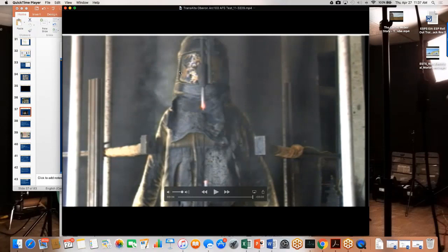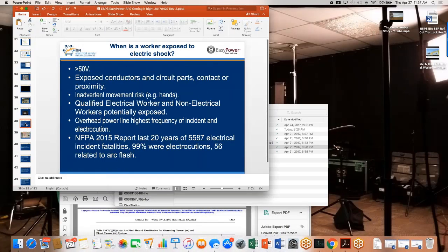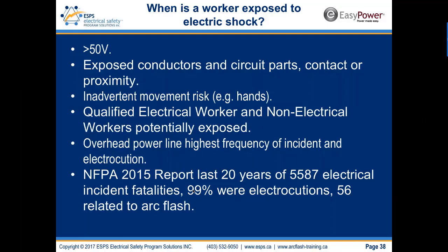That's what an arc flash suit will look like. That's what the arc flash suit hood lens will look like. It takes the heat, absorbs it. Heat continues to go through the garment, but only enough heat for the 50% probability of the onset of a secondary burn when you're exposed at the arc thermal performance value of the garment, the arc-rated garment.